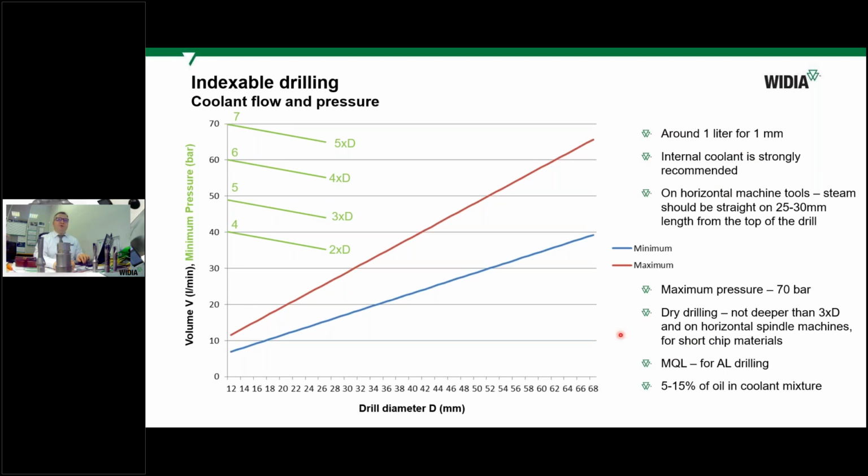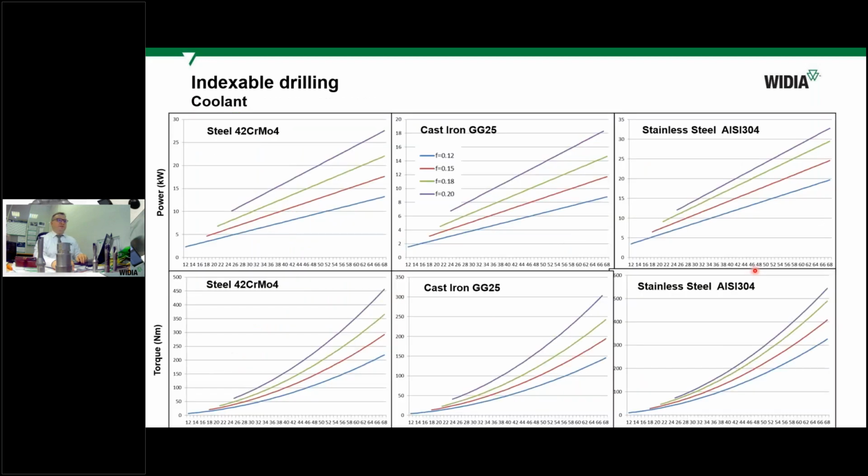So how to control the coolant flow? It's easy. You need to have a can, for example, a 10-liter can, turn on the coolant and calculate the time when it will be full. So it will be 10 liters per, for example, minute. And you can compare if it's enough or not, or you can ask the operator to increase the volume of the coolant.